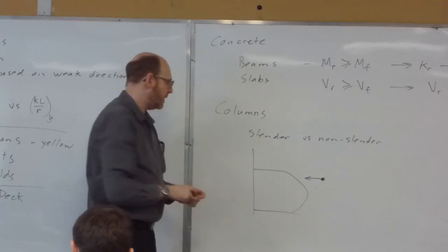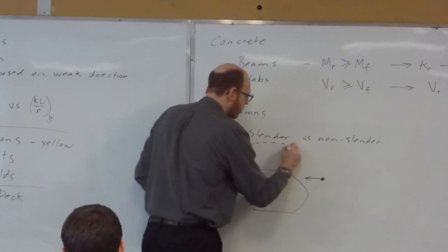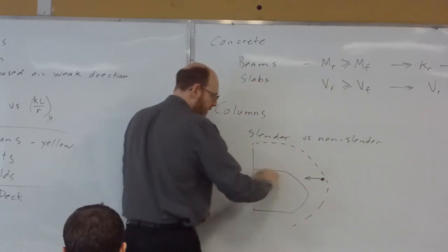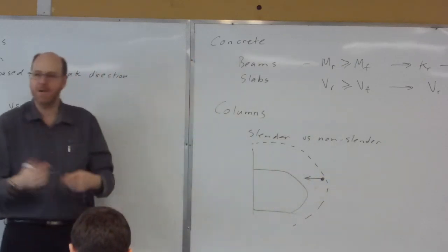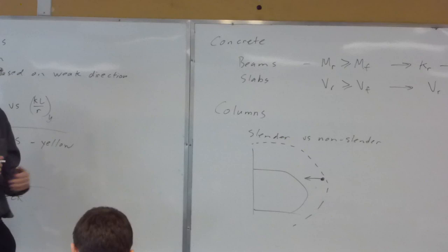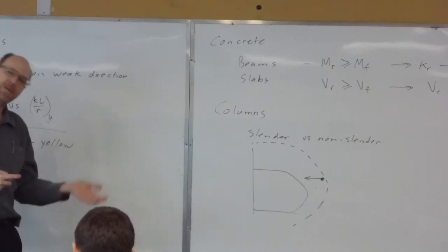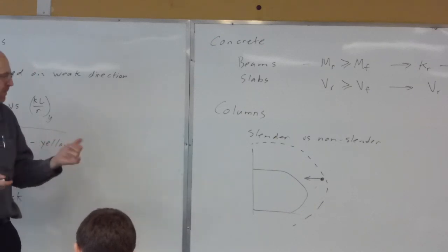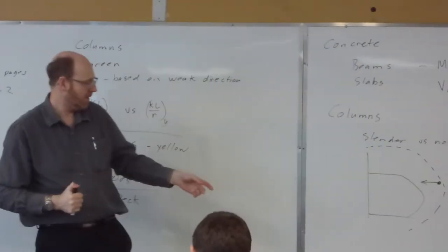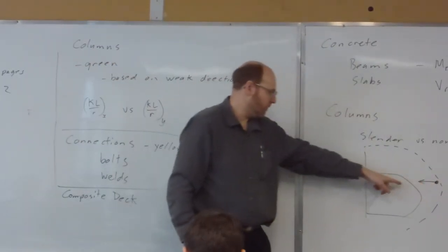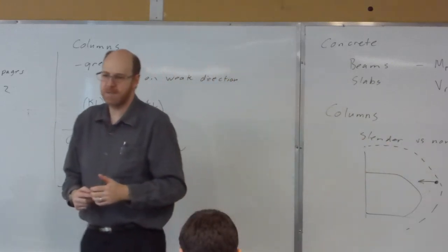So what you end up with is, if you're outside the curve, I'm going to take a look at the reinforcing ratio for an equivalent curve that will be out here somewhere, and the reinforcing ratio for this one, and I'm going to take something in about the middle. Not necessarily exactly the middle, you don't have to do an interpolation or anything in there, but you come up with a configuration that looks like it might work, and you try it again. And if it doesn't work, then you might have to iterate one more time, but you shouldn't have to do any more than 2 iterations on this. So a slight little difference in the slender case is that this point will move only in the horizontal. It doesn't move up and down. The P over AG remains the same.